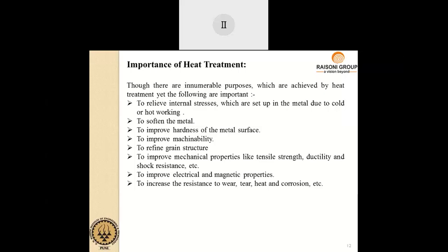What is martensite? Martensite is an intermediate phase between austenite and ferrite, because I am not allowing the austenite to get converted into ferrite. I am not allowing the crystal structure conversion from FCC to BCC because I am applying a very high cooling rate.